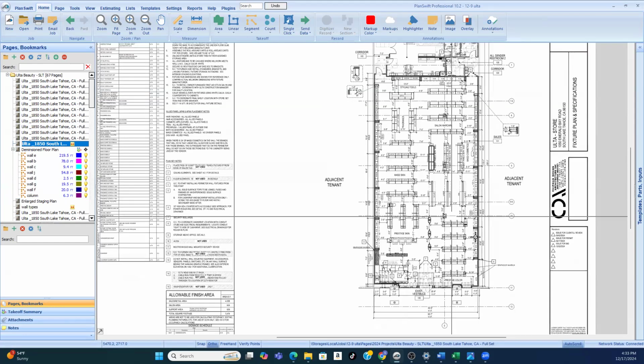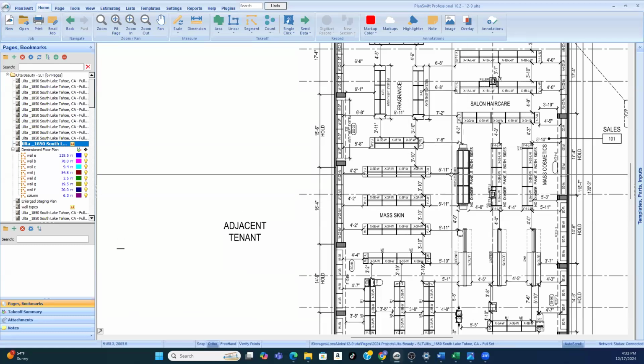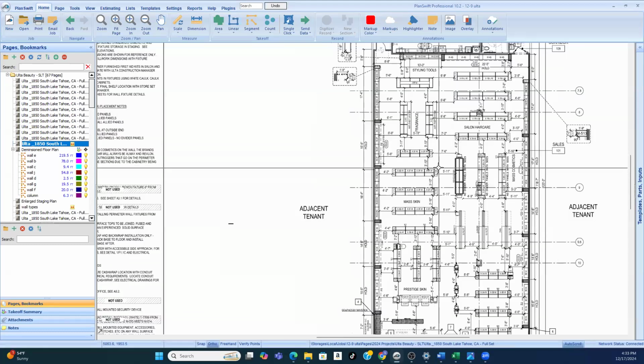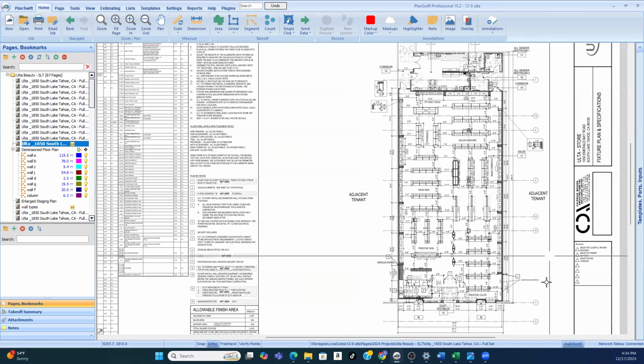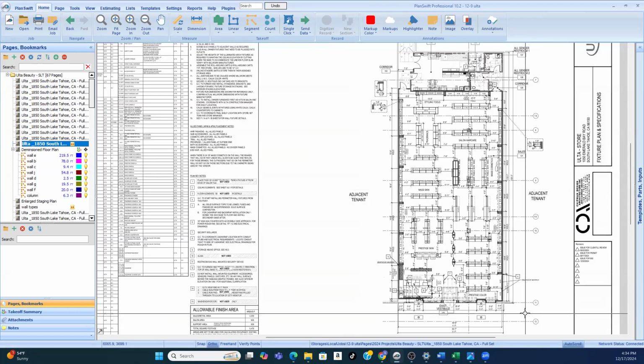Okay, so the first of the views is the most basic of the views, and that is what we call the plan view. So when you say send me the plans, that's just a generic term for construction documents, because plan is a way that you are looking at the sheet. It's as if you're hovering over the building. They took the ceiling or roof off, and you're hovering over it, looking down. And that's the plan view. So whether it's the floor plan, the fixture plan, the roof plan, the ceiling plan, all the plans, that's a particular way that you're looking at the sheet. And that's the most basic of the views.